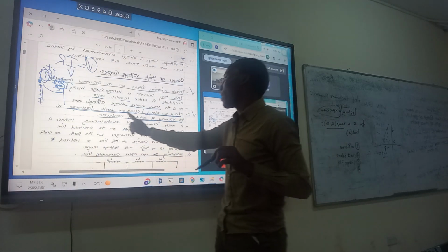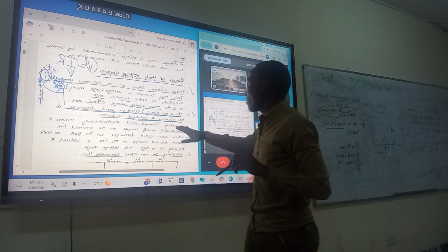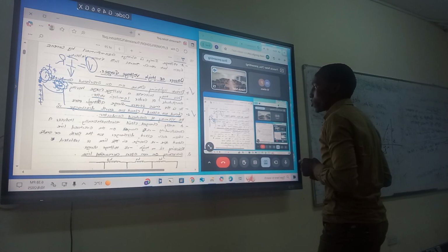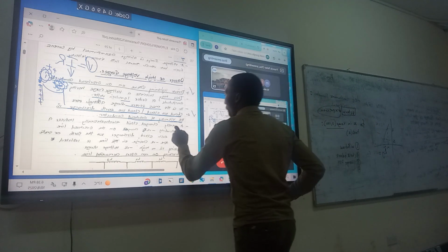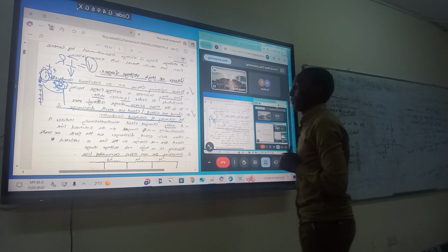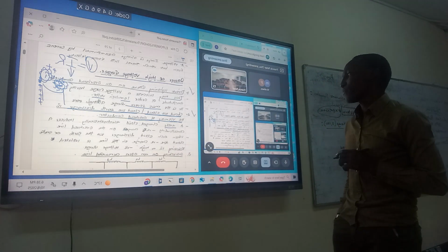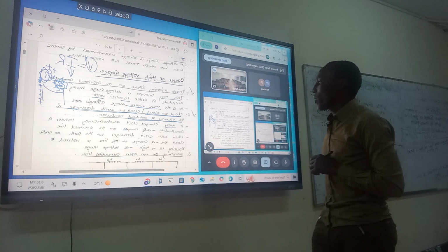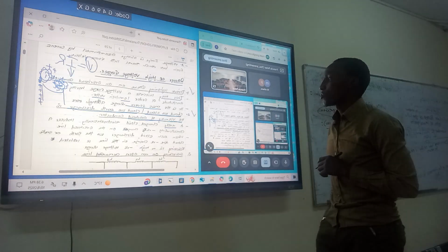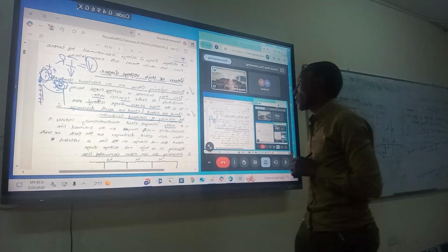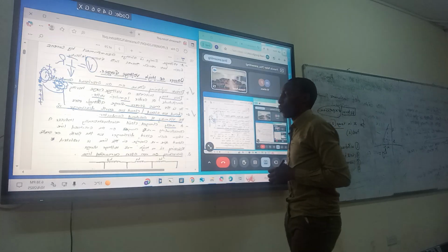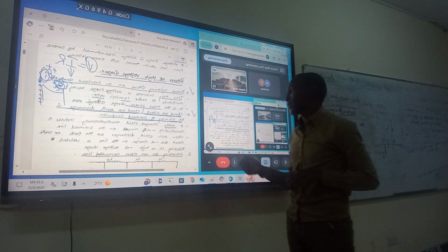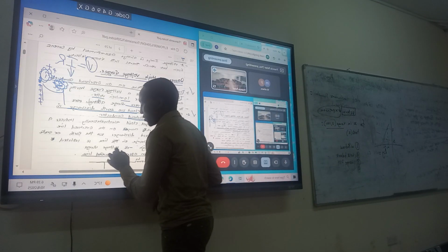That's why we are saying cloud to earth discharge in the vicinity of the overhead conductors. Therefore, a positively charged cloud electrostatically induces a corresponding negative charge on the overhead line, and when such a cloud discharges to the earth or maybe another cloud, then the negative charge on the line is isolated, resulting in a high negative voltage surge.